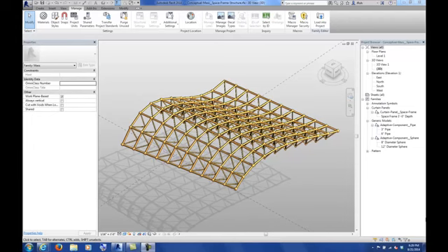So today what I want to do is really jump into working in the conceptual design environment within Revit. What we're going to be doing today is essentially building this space frame structure, and we're going to learn how to use parametric profiles as well as looking into adaptive components and also how they relate to the curtain panel pattern-based families that are within Revit.